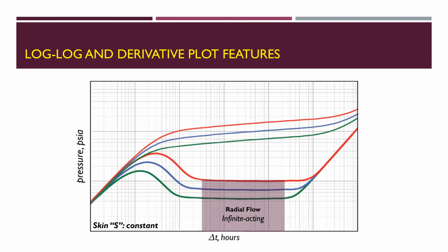And the last example here, the gap is in both the pressure change and the derivative as well. That means we have shifting. This shift is shifting down. Not only shifting down, even the radial flow has been extended, as you see, stretched horizontally. So the factor that is increasing here, I cannot consider as an independent factor. So in the model that you have considered, skin is constant, you will see this variation in both the pressure change and the derivative, moving down.